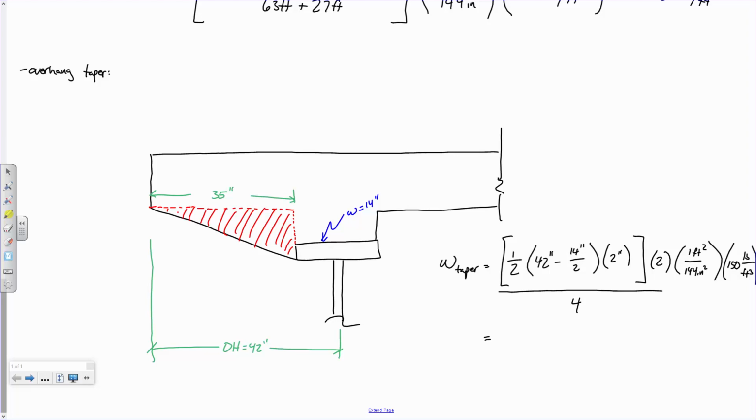Well, that's what he was asking. There isn't really a requirement. The reason that we've set one, though, is because I'm representing the decks to be flat. And that's fine for our purposes, but they really aren't. Usually, you're going to have a crown, like your 2%, for drainage and whatnot. So in order to set deck elevations, your formwork is usually attached between your girders. So the formwork and the slab ends up being a little bit raised.